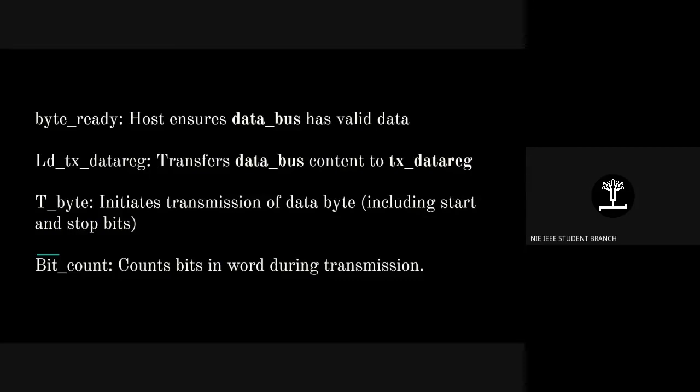Let's just go through the test bench ones, as we have been doing from yesterday. That's the basic thing. All inputs are registers. Output is the wire, just how it is here. Just paste it here. I've named it TB_UART_TX just to know that it's a test bench. A test bench is not a module. Nothing gets synthesized. All it does is provide stimulus to this.